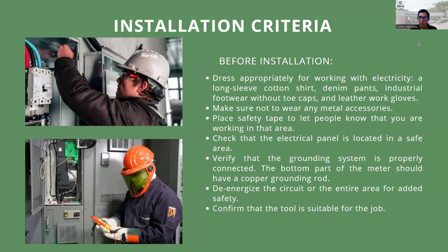First, we have the before installation. In this case, dress appropriately for working with electricity: a long sleeve cotton shirt, industrial footwear without steel caps, and leather work gloves. Make sure not to wear any metal accessories. Place safety tape to let people know that you are working in that area.